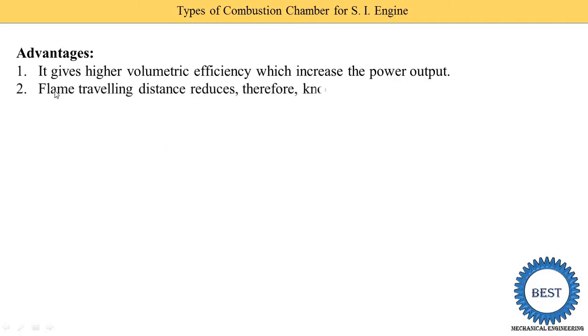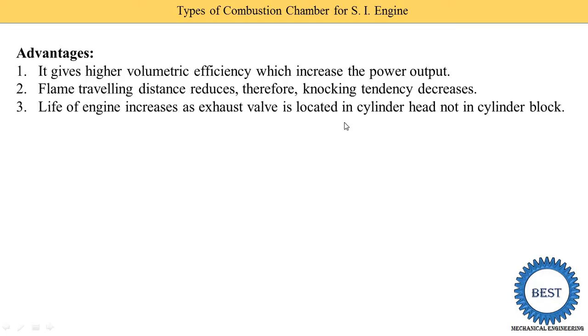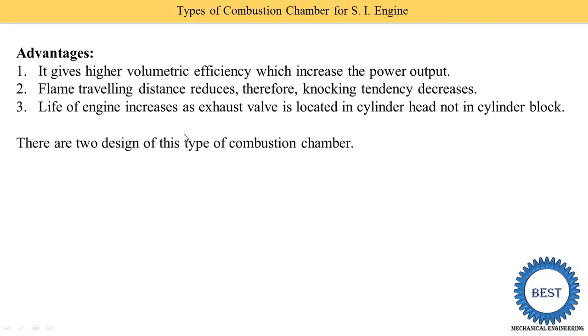Flame traveling distance is reduced, therefore knocking tendency is decreased. The spark plug is provided at the center, so flame traveling distance is reduced. Life of the engine is increased, because the exhaust valve is located in the cylinder head, not in the cylinder block. So the life of the engine is increased due to the exhaust valve being located in the cylinder head, not in the cylinder block.